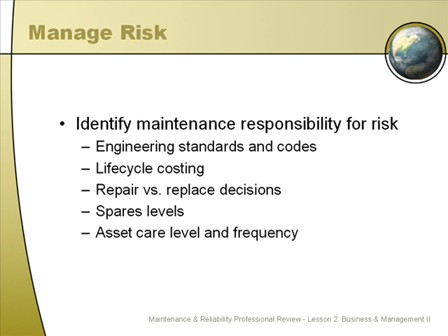Fourth, spares levels. As your proactive maintenance approach becomes a way of life in your facility, you are going to be able to adjust your spares levels in your storeroom inventory downward. In fact, a lot of the inventory that you carry will become unnecessary and different things will become more important.